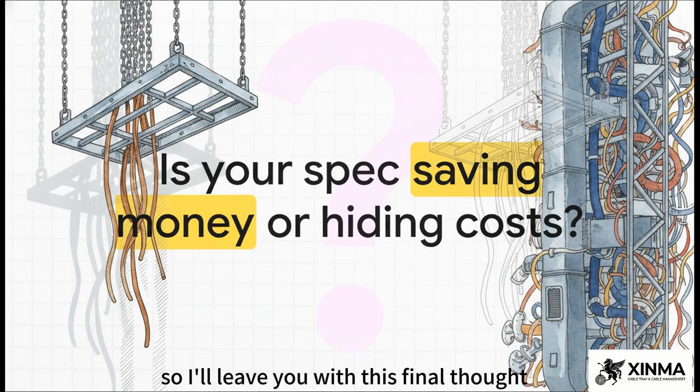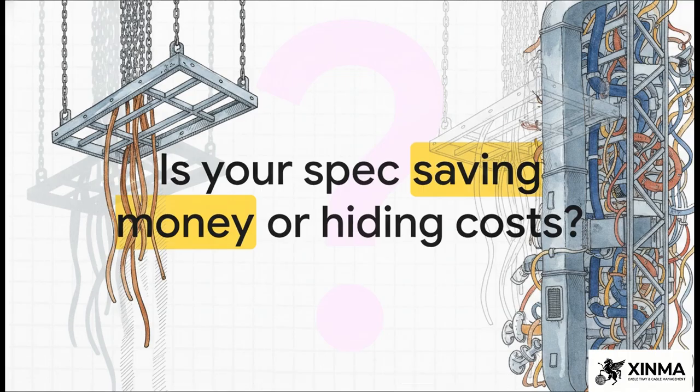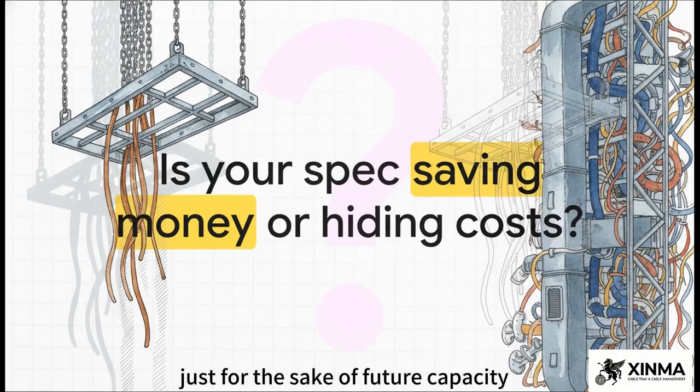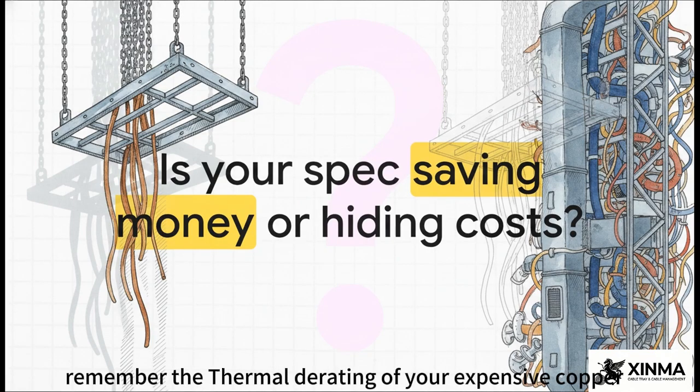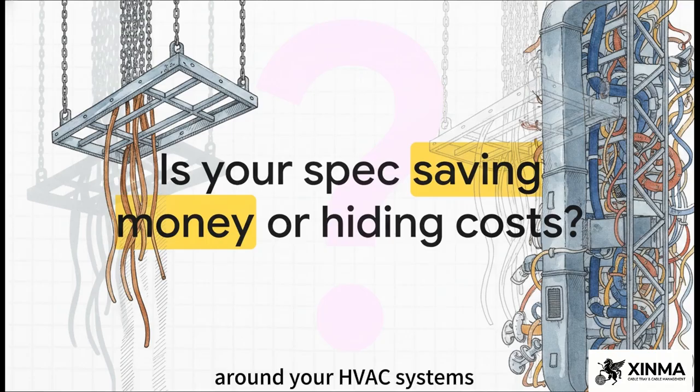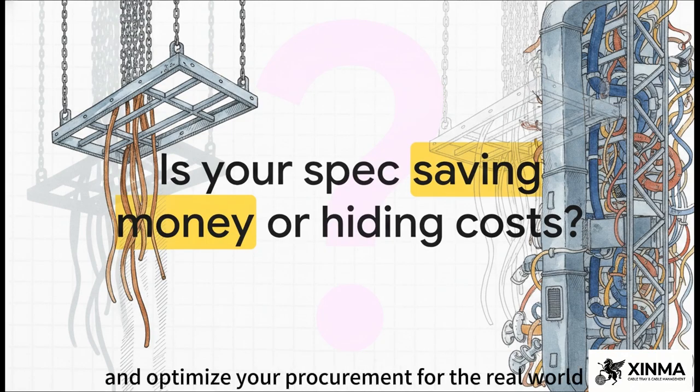So I'll leave you with this final thought to challenge your next big project and encourage a smarter, space-optimized purchasing strategy. Is your current cable tray spec really saving you money, or is it just hiding future costs? The next time you see a massive tray size specified just for the sake of future capacity, remember those hidden hanger costs. Remember the thermal derating of your expensive copper. And don't forget the absolute spatial nightmare it might cause around your HVAC systems. Think structurally, think thermally, and optimize your procurement for the real world.